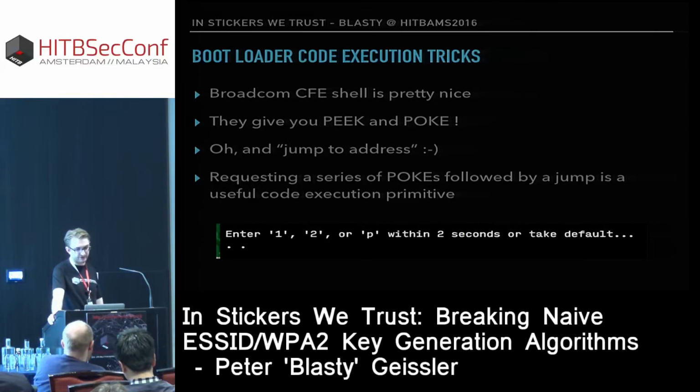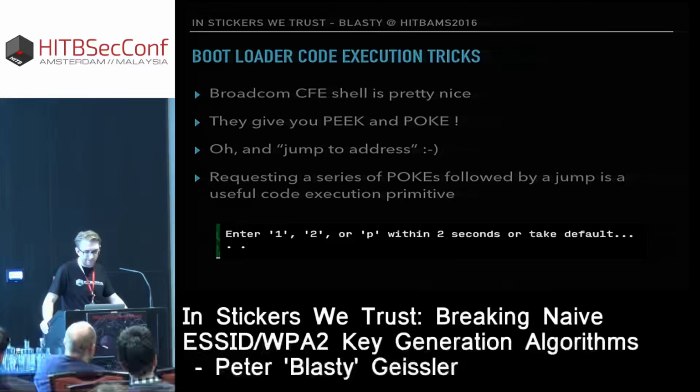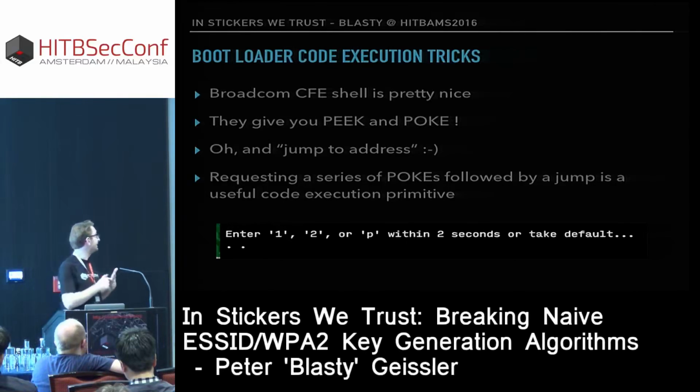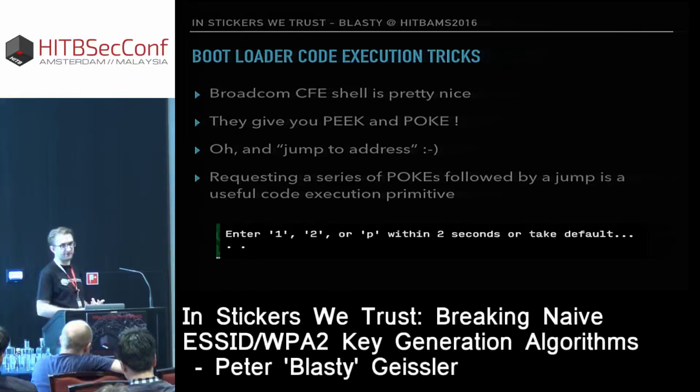But then there's also the option to press P, right? And when you press P, you get thrown into this really nice menu. I wish I had a screenshot over here, but I don't. And the menu gives you a bunch of options. One of them is boot the system as normal. The other is boot the system from TFTP. There's an option to read memory, it's a peek. There's an option to write memory, like a poke. And then there's an option to jump to an arbitrary address of your liking.